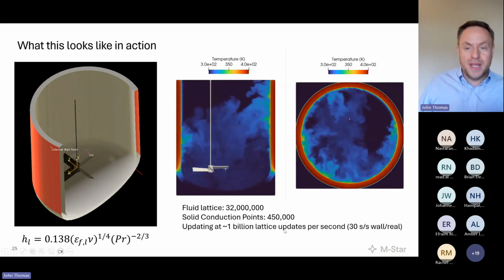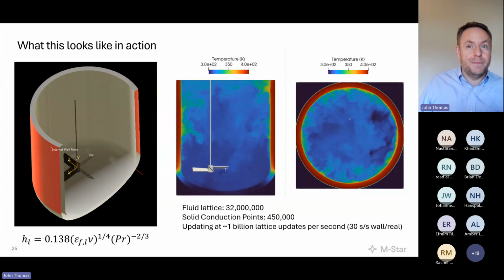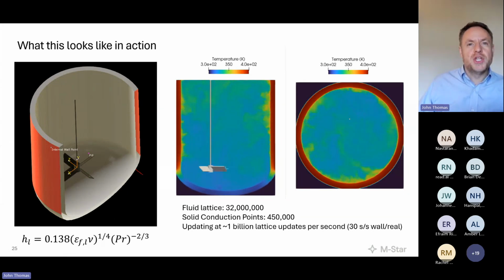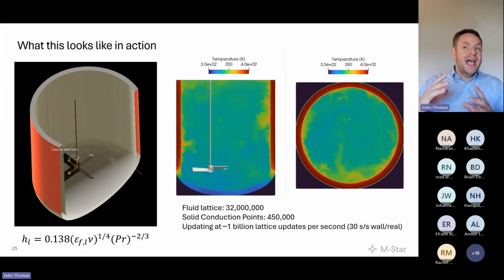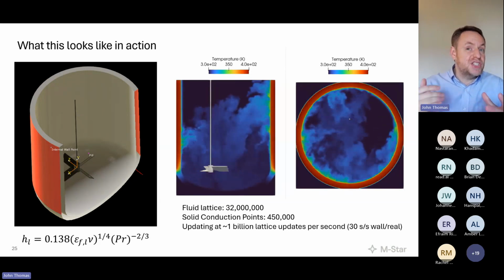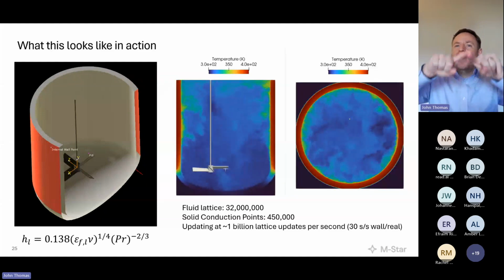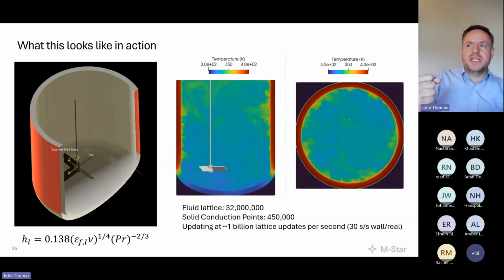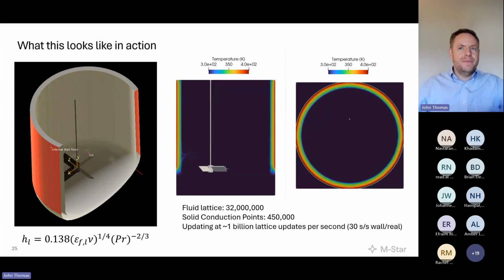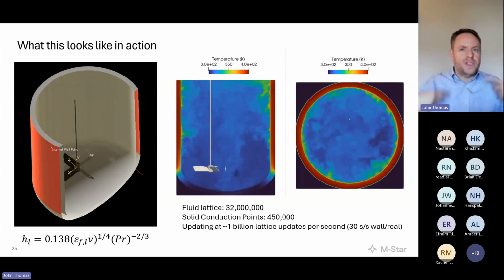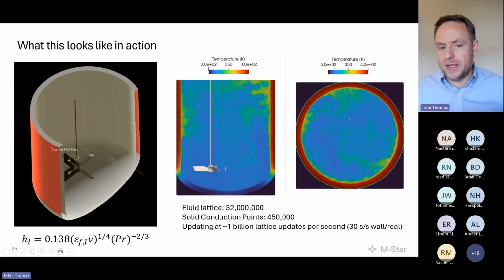There's a lot going on here. We have conduction, convection, advection, but importantly, it's all built into the code, self-consistent and all happening in tandem. So if I have temperature going into the fluid and that fluid becoming less dense due to buoyancy, or I have a viscosity change in the fluid due to change in temperature, that's all self-incorporated. I can immediately see how temperatures can inform density, maybe inform viscosity, and inform the solution of our Stokes equations. I'm not layering a temperature field on top of a fluid field. I'm solving all these physics in tandem, which is quite compelling, I think.